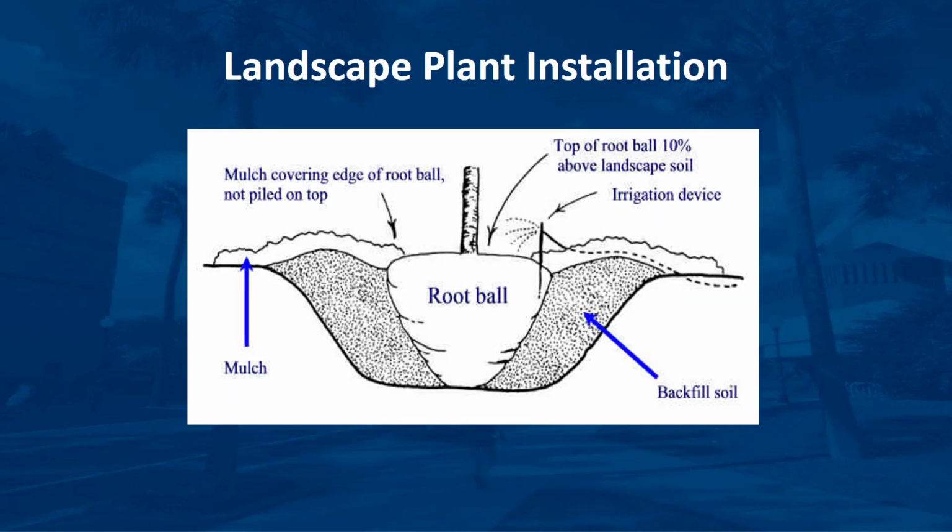Before digging the hole, 1. Remove all soil from above the topmost root. And 2. Measure the distance between the topmost root and the bottom of the root ball. Dig the hole about 10% shallower than this depth and as wide as possible, at least 1.5 times the width of the ball and even wider in compacted soils.